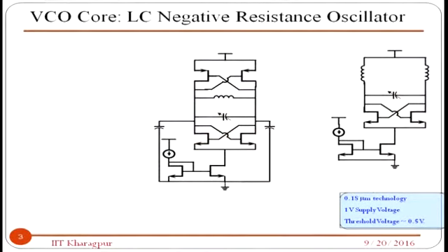Now, coming to the next one, you can have both of these. Again, the constraint is that the VCO is a PMOS cross-coupled and NMOS cross-coupled pair. I will let you know why you use both, a complementary architecture, with this tail current through a current mirror source, and this is a variable cap. It can also be done with a simple NMOS, or what you call pseudo CMOS oscillators. When you have a 1 volt supply here, biasing these two transistors may be difficult, so you can go to this pseudo CMOS or simple NMOS configuration.